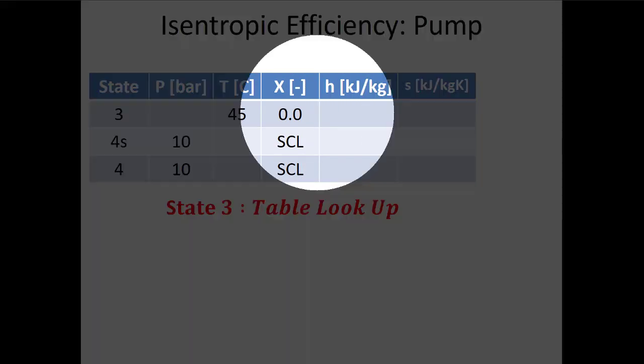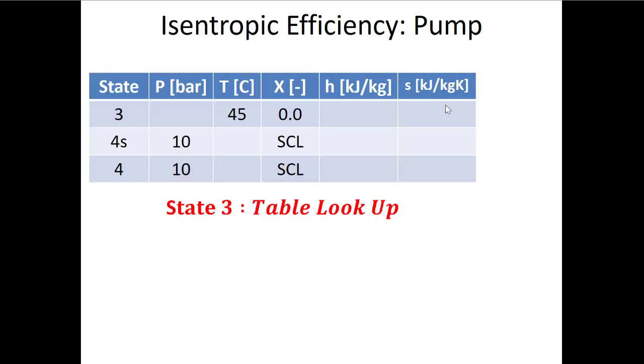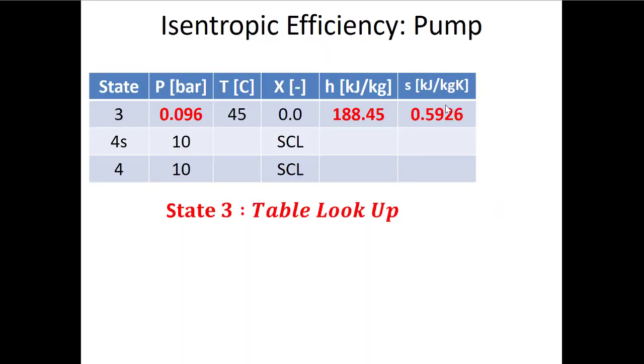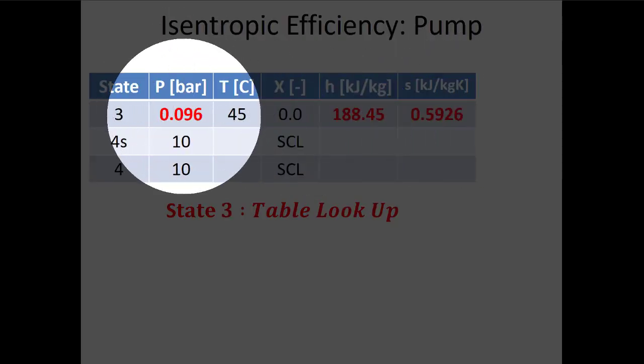So this H is going to be HF and S is going to be SF. So I just put that information in. Now, maybe you remember, but when we go through ideal pumps, we're going to use this equation, specific volume times the change in pressure. So what I've done here is I have added...